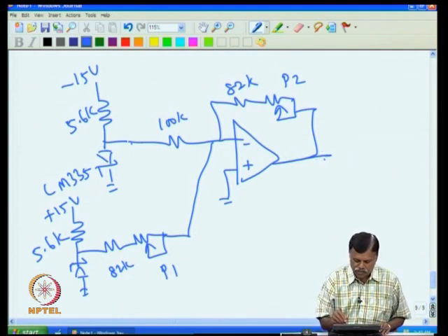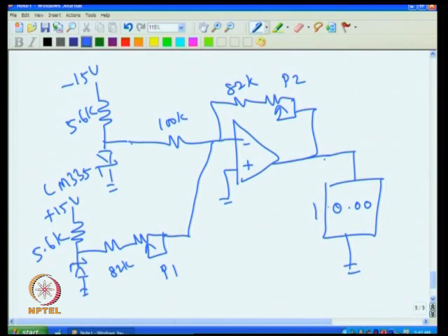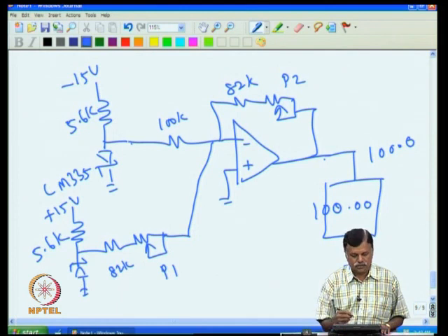So this also can be done to give positive voltage. Now all that needs to be done is you connect the meter here, and that will show 0 degree C as 0, and 100 degree C it will show 100. And that can be achieved. For example, I can connect a voltmeter of 1 volt full scale. Then when 1 volt comes, it definitely will show this. All that is needed is I put on a dot, and that comes as a display. Now in this case we have just taken a design example, and we have done it using the summing property of the operational amplifier.